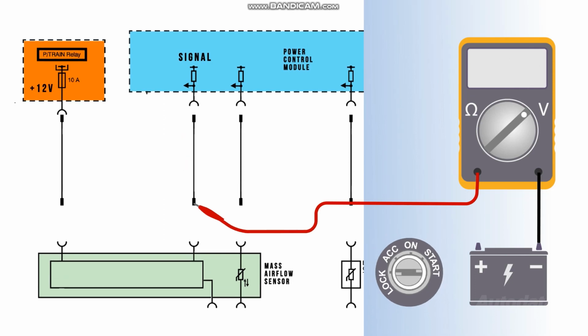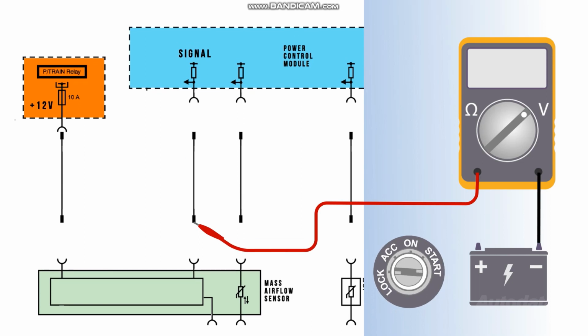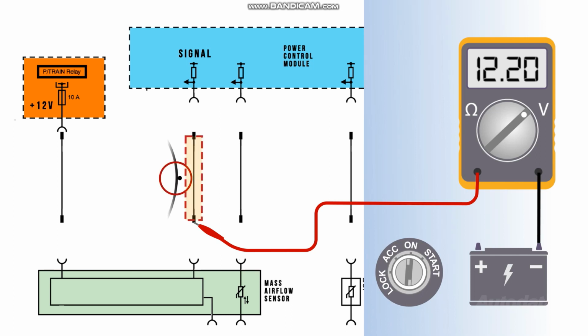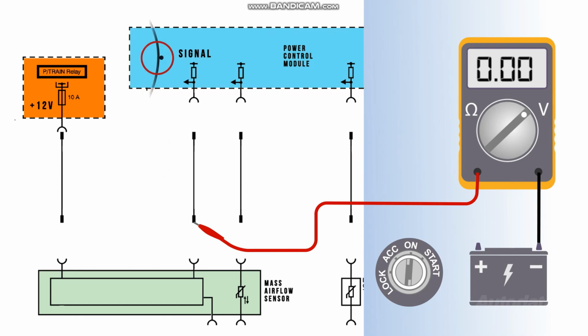Turn the ignition off and disconnect the ECM. Turn the ignition on and watch the display. If the voltage is still present, the short is in the harness between the two connectors. If the meter display registered 0 volts with the ECM disconnected, the short may be in the ECM or another circuit from the ECM.